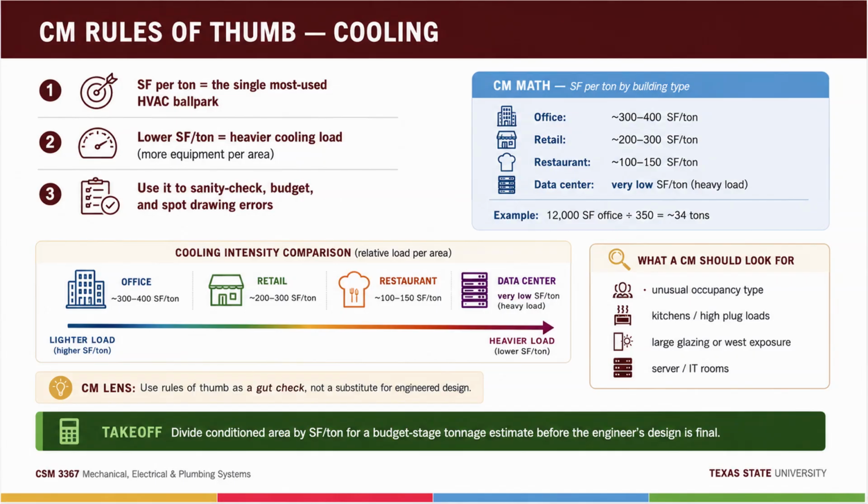Equipment, plug loads, third. Computers, monitors, copiers, coffee makers, refrigerators, servers. Same physics, same constant. Nameplate watts to BTUs at 3.412. With a caveat: equipment rarely draws nameplate continuously, so engineers apply usage and diversity factors rather than adding up every label in the building. Typical offices carry another watt or so per square foot for plug loads.